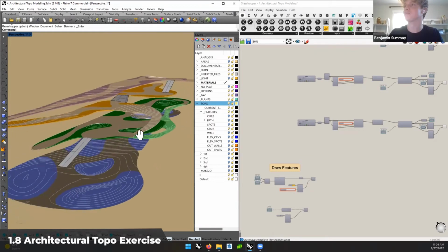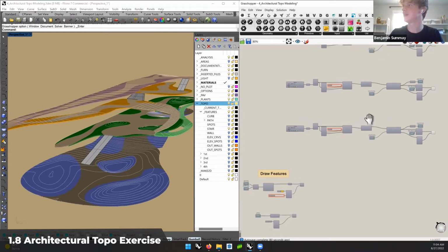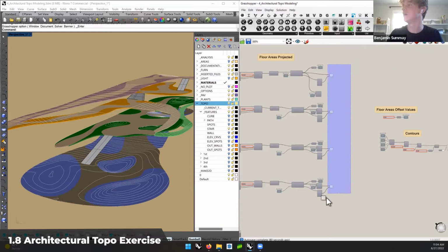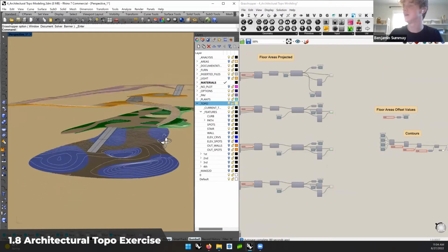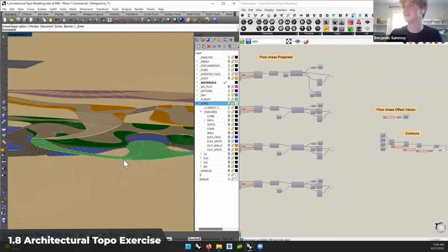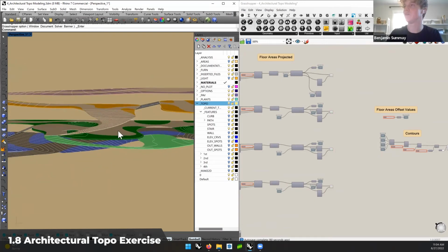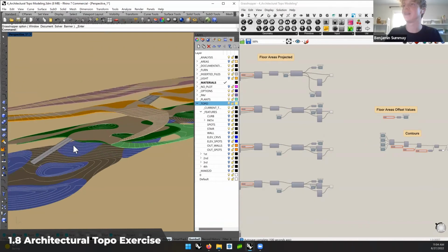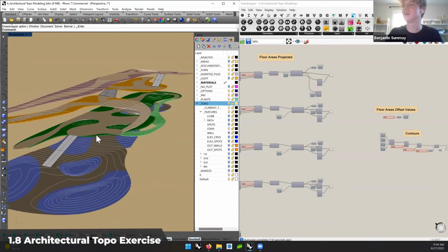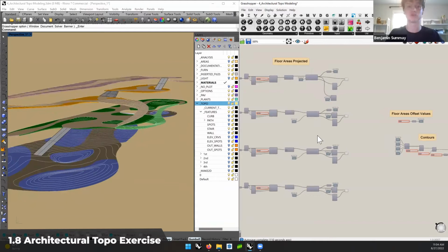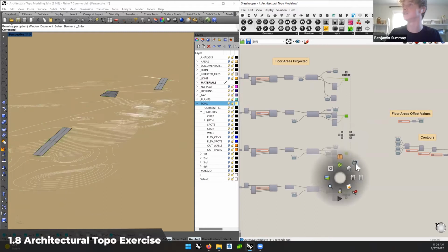And so we'll jump into what's happening at each floor, how we're building this, and how we're creating these different seamless elements. Typically when you're working with a mesh, it's the Delaunay mesh concept within Grasshopper, which creates a single surface of a mesh. So getting these fine lines and edges can be difficult unless you're working with these projected areas that we're using here to cut out different zones in the floors.